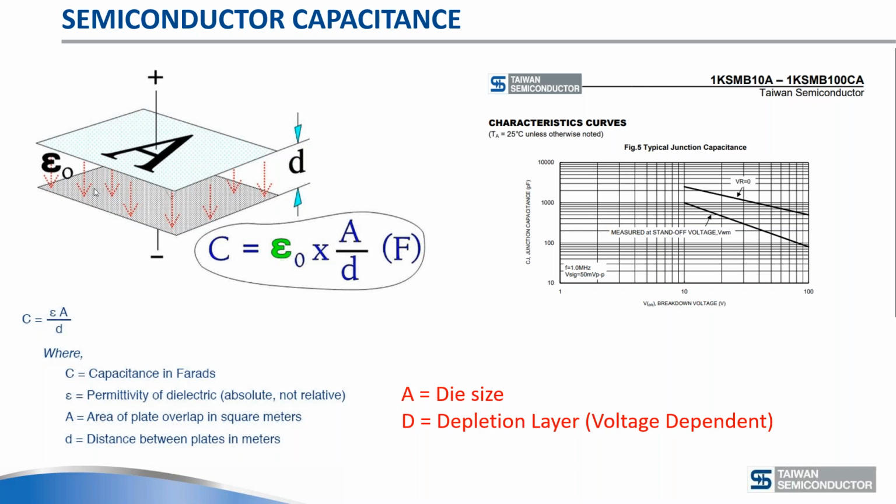If the voltage goes up, the depletion layer also widens, and that is how the D behaves on the reverse side. That's how you get the capacitance to go down as the voltage goes up. The voltage goes up, the depletion layer goes up, so the capacitance goes down.